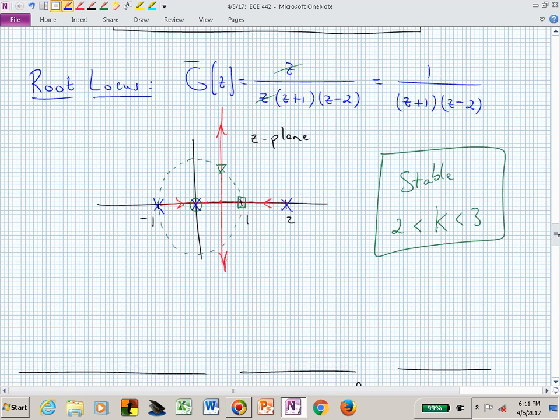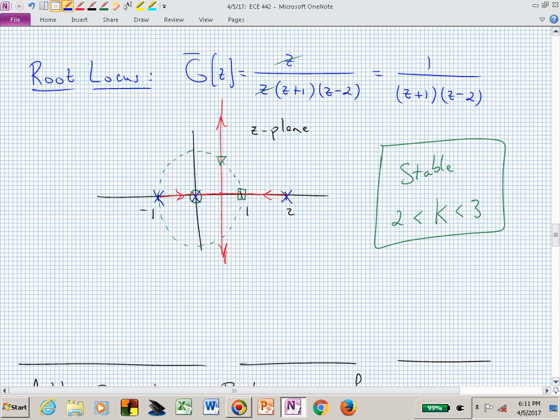So the question is, do we want to put a closed loop pole right on the unit circle? And for those of you listening to this, you have no idea what just happened. But if you put something on the unit circle, what's going to happen? If that mode gets excited, it's just going to sit there and shake, right? And it will never damp because it's not inside the unit circle.